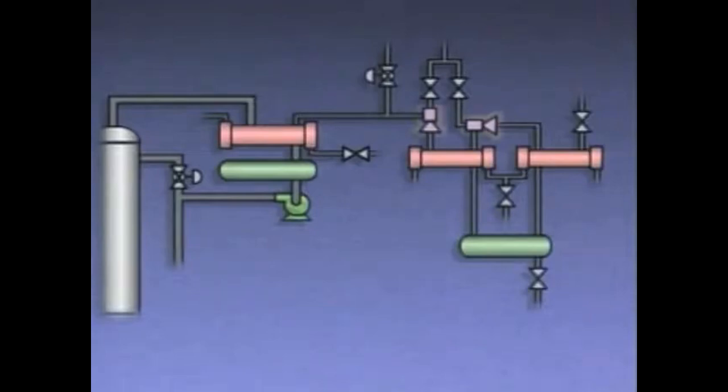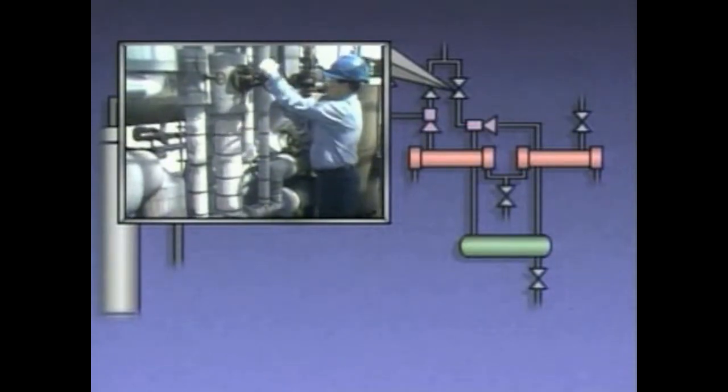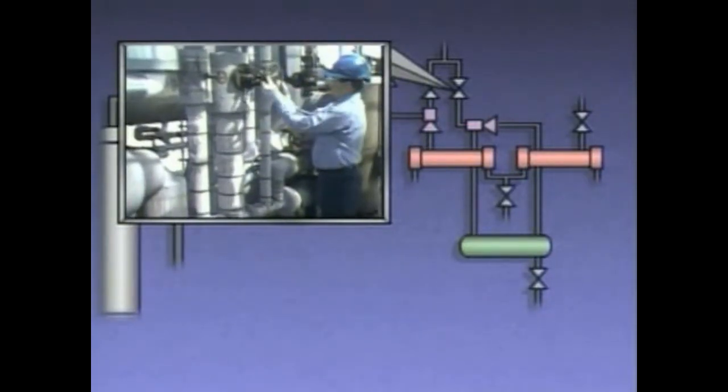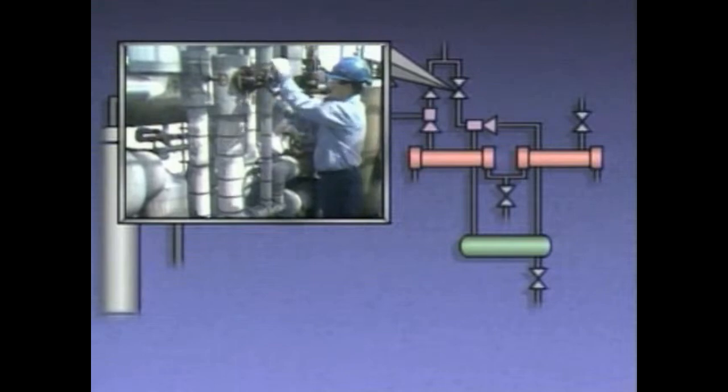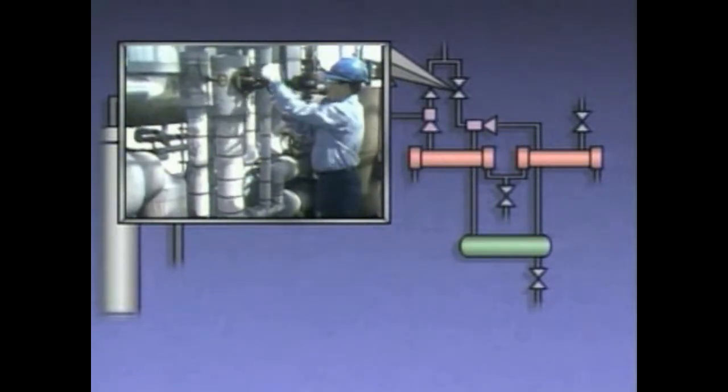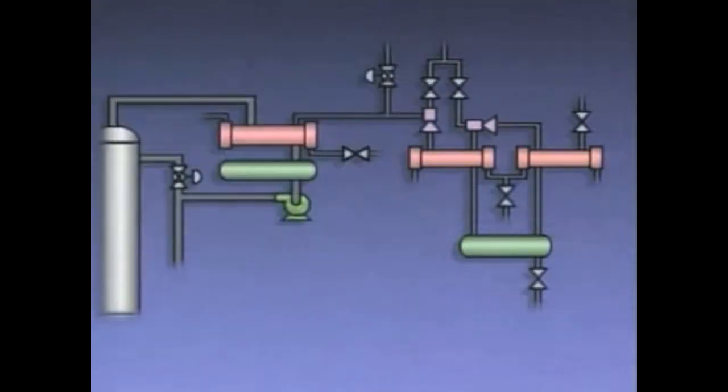In this system, 2 steam jets are used to maintain the vacuum. The operator starts the jet that's farther from the column first by slowly opening a valve, which admits steam to the jet and gradually warms the vacuum system. Once pressure in the column drops, he opens the valve for the other steam jet in the same manner. When the vacuum in the column reaches the specified amount, preparations can be made to heat the mixture and begin